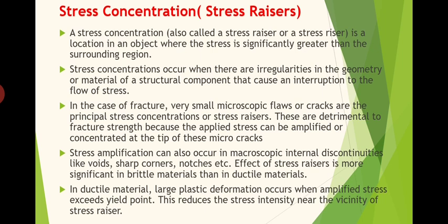If we apply a particular stress on a material, in practice the stress is not uniformly distributed all over the body. Theoretically we assume that stress is uniformly distributed, but if some micro cracks are within the material, these cracks will act as stress concentrators, or we can say the stress experienced at those defect points is very high compared to the stress acting on the other regions.